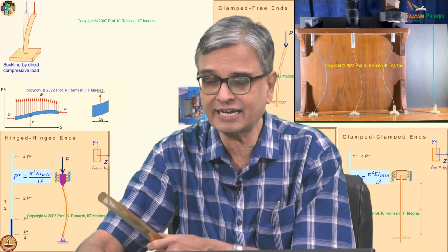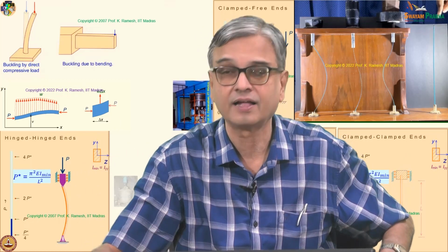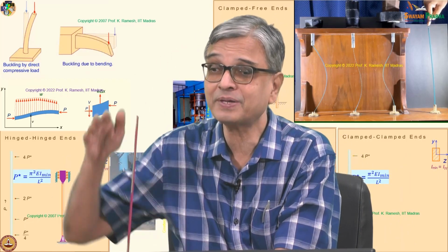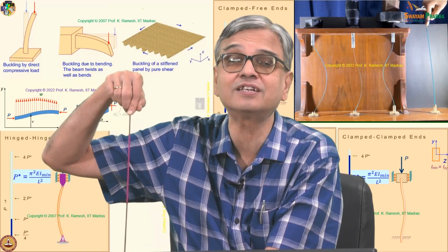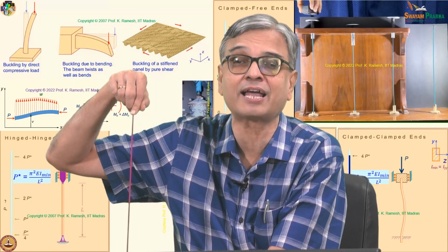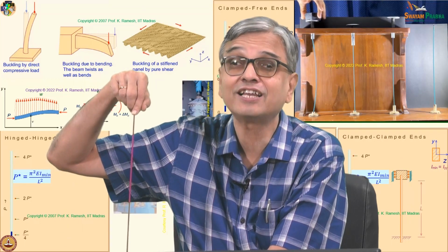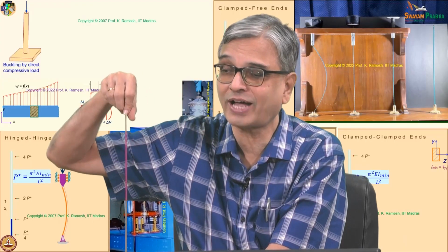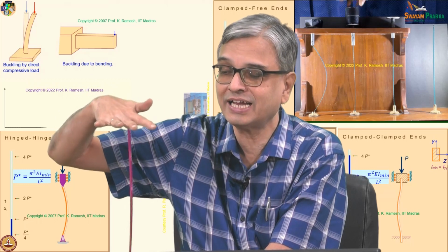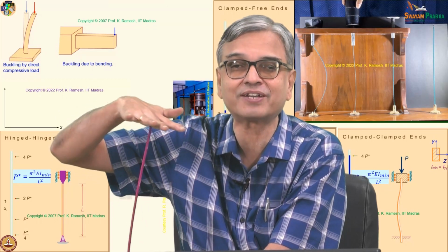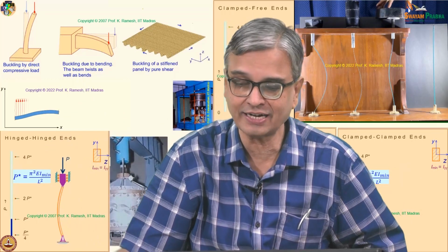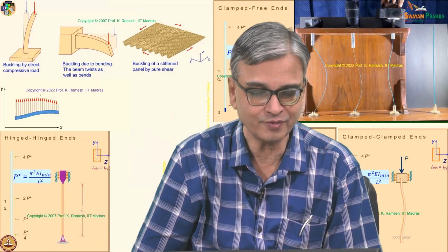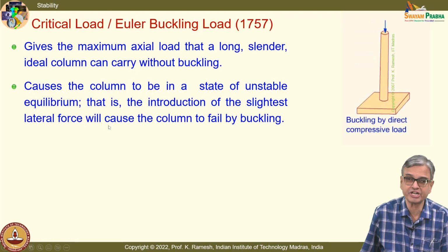Suppose I take a rectangular cross section. Here what happens? You should be able to say, I have the rectangular cross section, in which way the probability of buckling can happen. Why is it so? Very good. So, what happens is it will buckle in the direction where it has the least moment of inertia. Fine. So, I have also modulated the expression in that fashion.